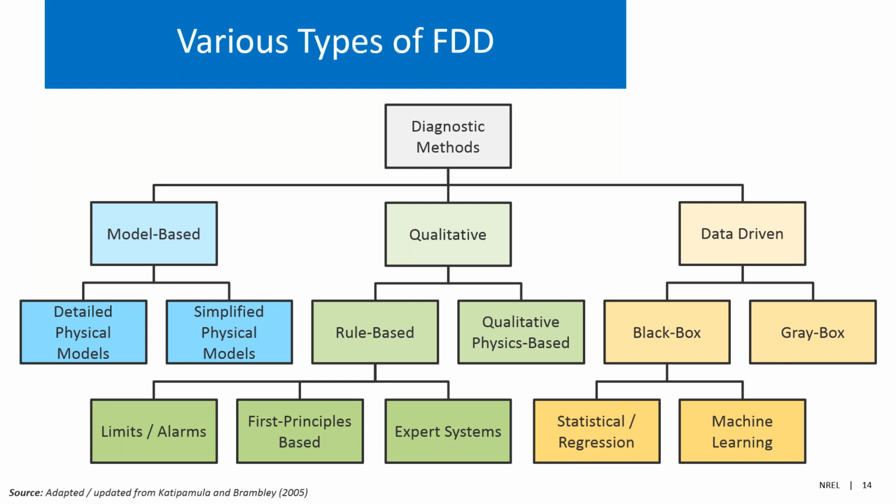Basically the idea here is that if in the past your building has been performing pretty well, you can use the data to build either a statistical model or some kind of machine learning model to predict how the building should perform in the future for a similar set of weather conditions or occupancy patterns. Then you can compare what you're actually seeing to this past performance and to your prediction and see if there's an issue. If there's a discrepancy, you can flag that as a potential problem and flag it as a fault.